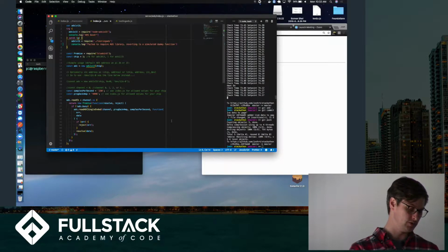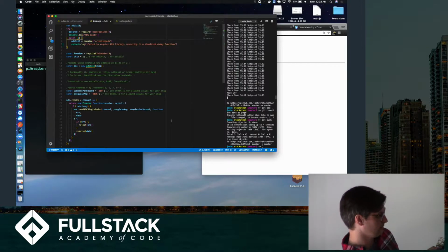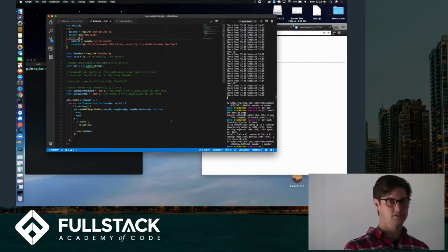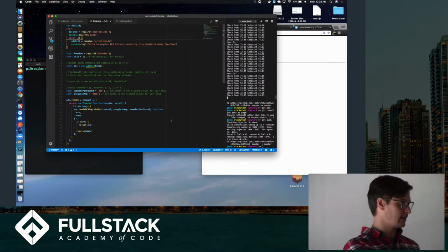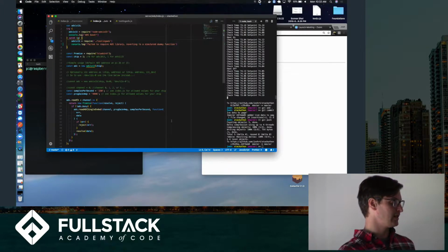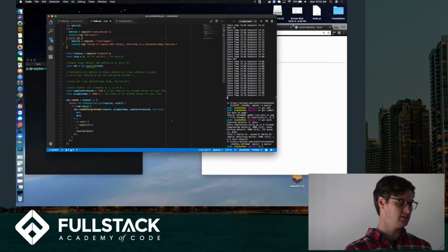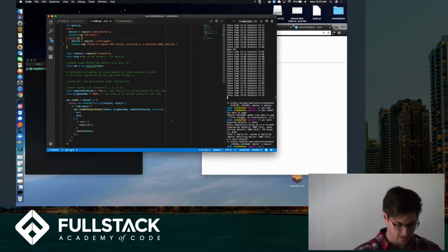But unfortunately, it's only got digital inputs and outputs, so in order to read in a temperature, and I've got a little thermostat here that reads temperature and a dial here for set point, and in order to read those values from the resistors, you had to have an analog to digital converter. So there's an extra chip up here that talks over a data bus to the Raspberry Pi using a library called I2C. It's a type of data bus. So I've got that set up.